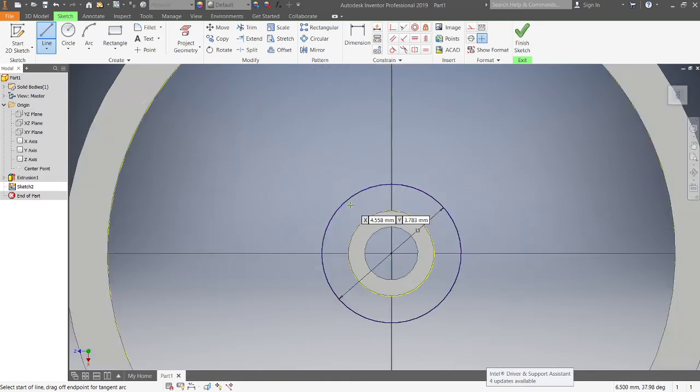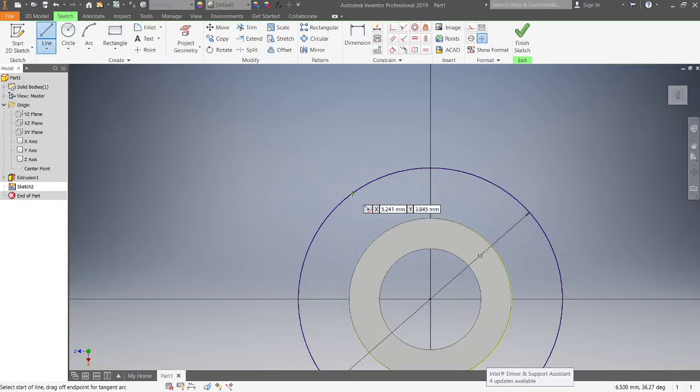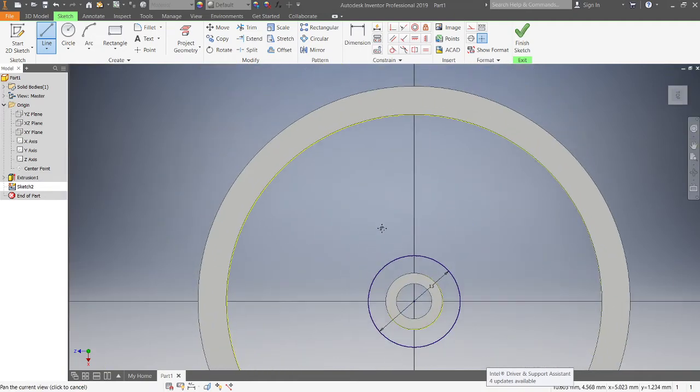Make sure that when you do your line tool, you bring that point right here. If you have a look next to this X here, as it snaps to that line, there's a little symbol there, like an arrow. So that means it snapped to that line. You want to make sure it snaps to that line, wherever you put that in.